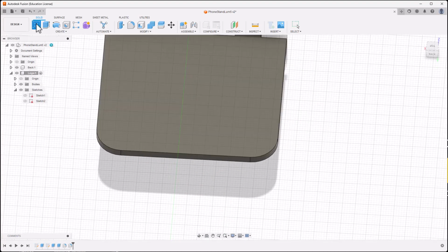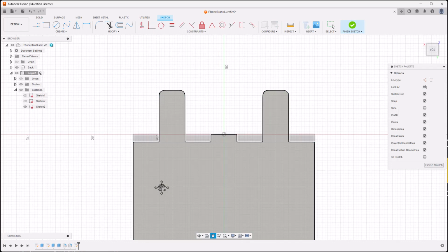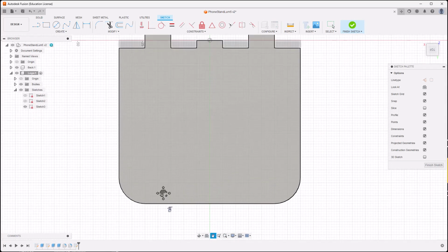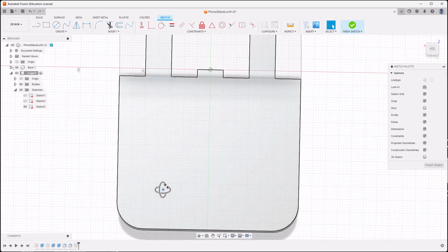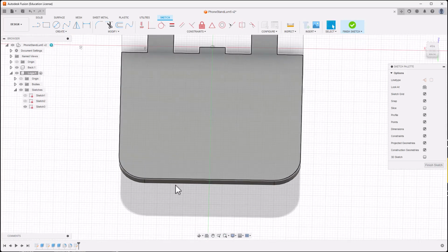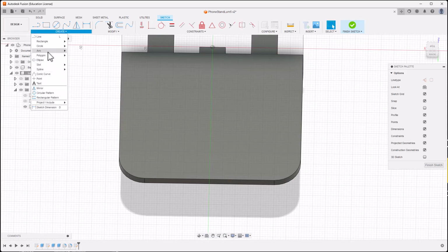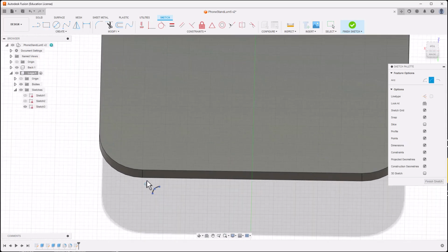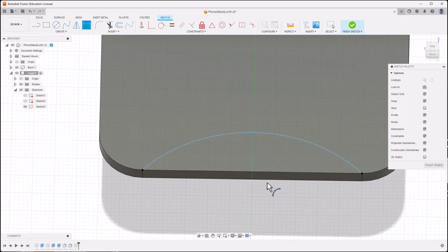So I'm going to go ahead and create sketch. Start here. I'm actually going to do two things. So let's do that arc. I'm going to turn this so I can see those fillet edges or those fillet marks. Create arc 3-point. Started this one. Notice that box shows up to tell me I'm right there. Here. Pull this out a little bit. Dimension it by hitting the D key and clicking on it. And this one is a radius again of 35.